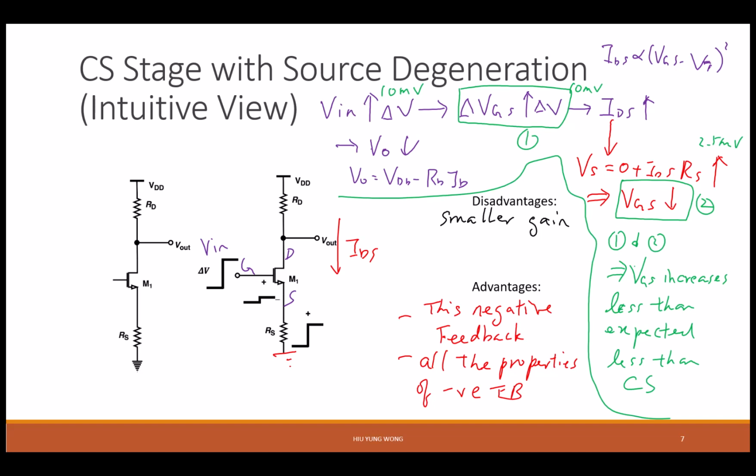Then you want to see what happened to the transistor. In all the transistor equations, it is delta VGS, right? So what happened to delta VGS when you increase V in by delta V? I think you will say it increases by delta V. Just short-sighted thinking, right?